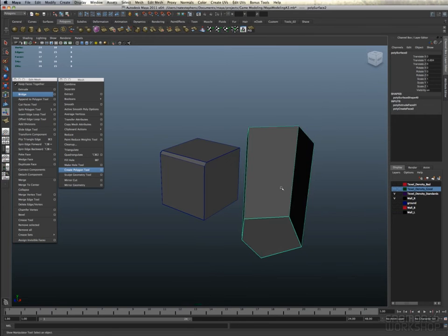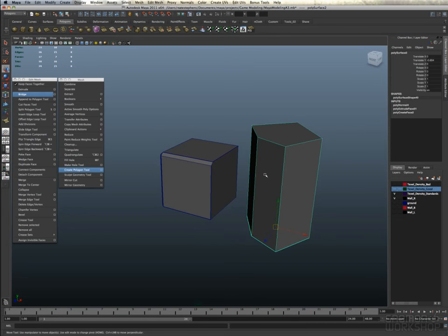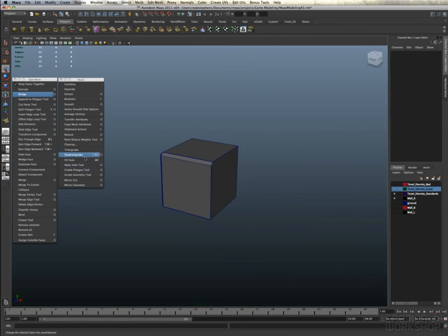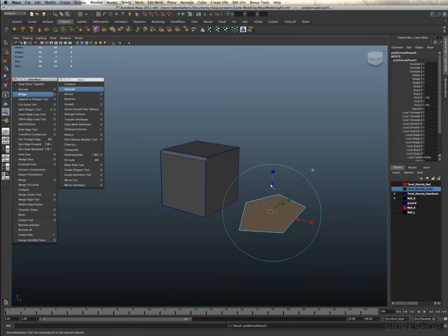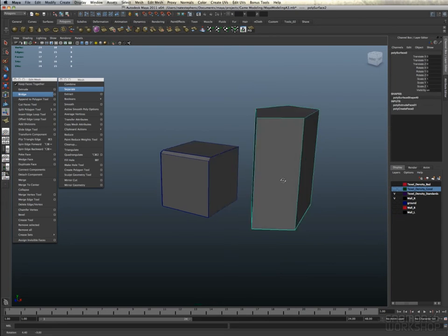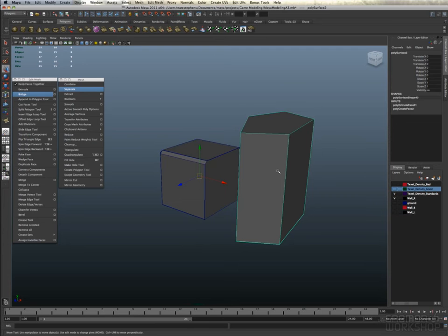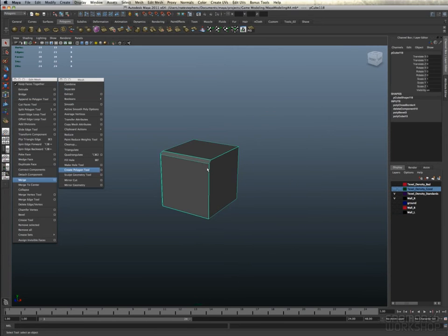But if I toggle the back face, you can see that all the faces have been reversed. And this happened because using the Create Polygon tool, I clicked clockwise. If I was to have clicked counterclockwise, like so, then when I do my extrusion, all the normals will be facing outward, which is what we want, and we won't have to reverse any of the faces. So using the Create Polygon tool, it's important, when you're drawing out your polygon, to move in a counterclockwise fashion.